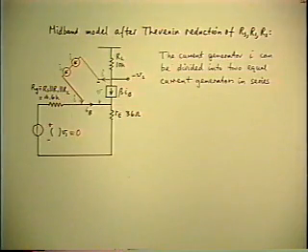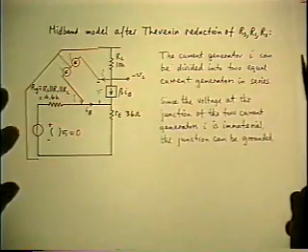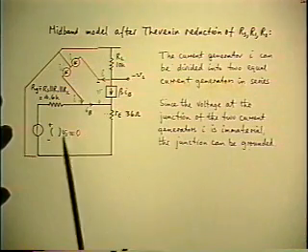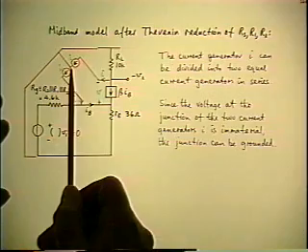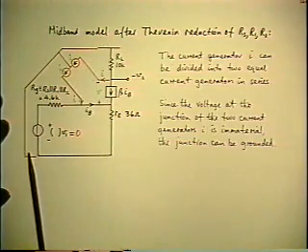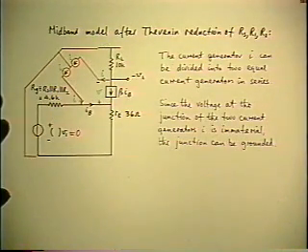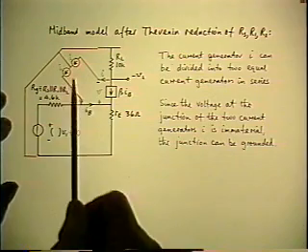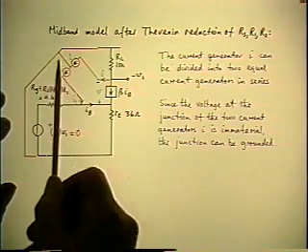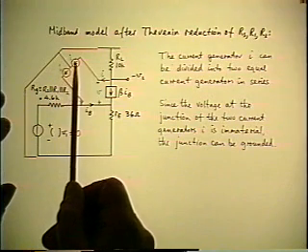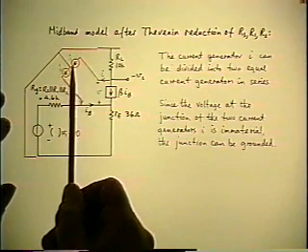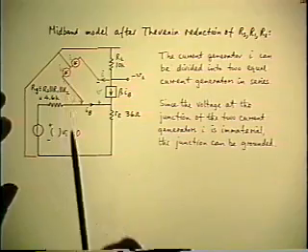As usual, the simplest value to choose is 0, 0 being ground in this case. So if I connect this node to ground, AC ground, still nothing is any different. There's no current in this path connecting the node to the two grounds, because the total current I out of this generator goes into the next one.